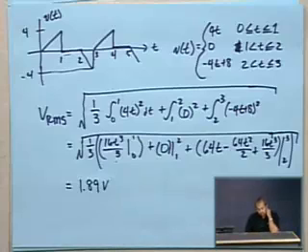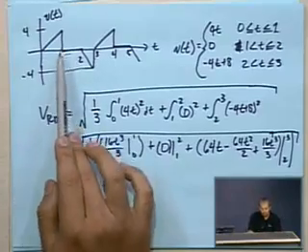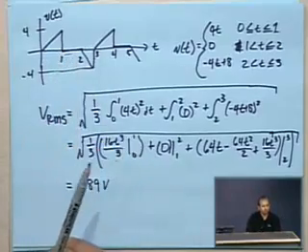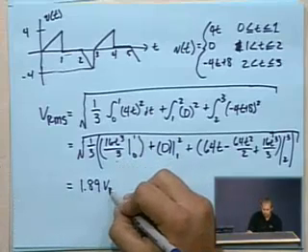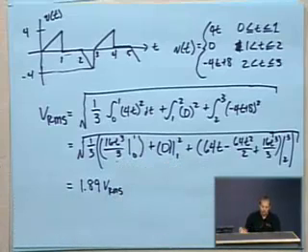And so I guess the nice thing about RMS in this case is it's allowed us to take something relatively complex, like this goofy, piecewise, almost sawtooth waveform, and quantify it as just a number. Yeah, it's 1.89 volts. And usually we'll tack on a V_RMS, or a subscript of RMS, to make sure that it's very clear that what we're dealing with is a root mean squared value and not a peak value.